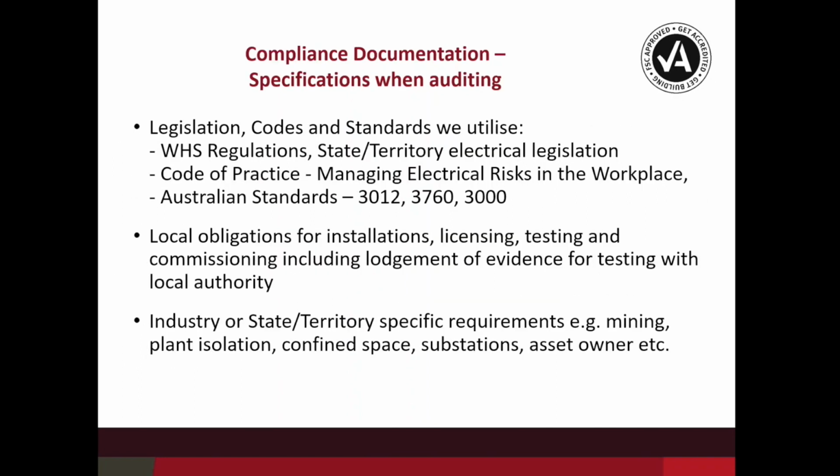What do we use when we go through audits? First step, obviously, is that we look to the state and territory regulations. There are some states that have an Electrical Safety Act and safety regulations that are applicable to what we look at. There are other states that don't, and they refer back to Australian standards and codes of practice, which we use. So typically we have the code of practice for managing electrical risks. We have the Australian standard, more prominently AS/NZS 3012, which is probably the key standard that we go to. AS/NZS 3760 is a support standard, which talks about testing and tagging and things like that, but again, it's actually superseded by 3012 in a number of areas.